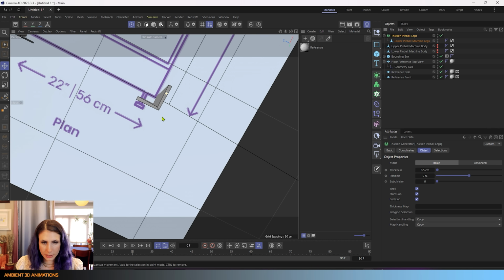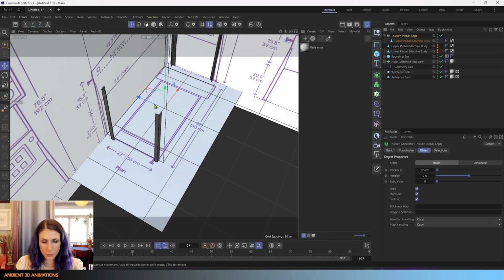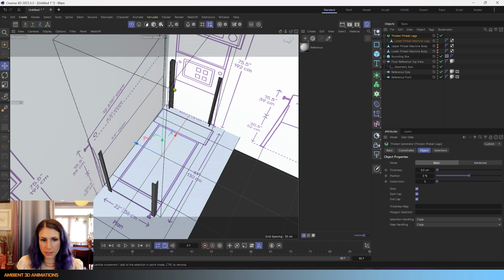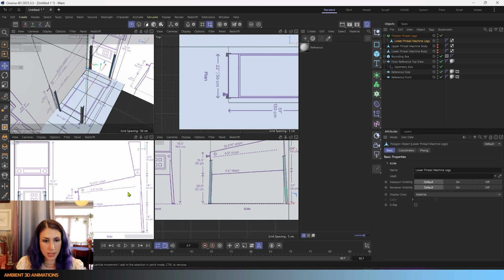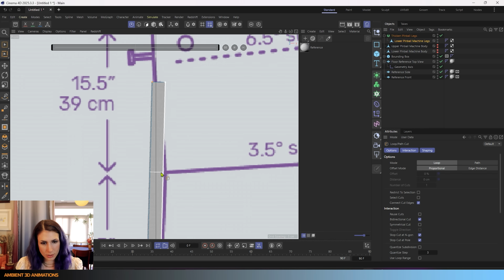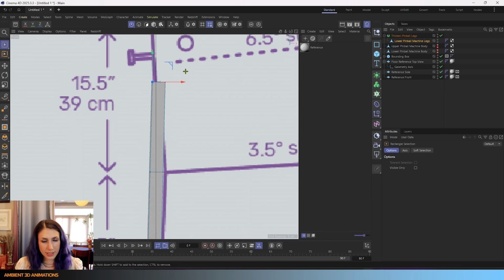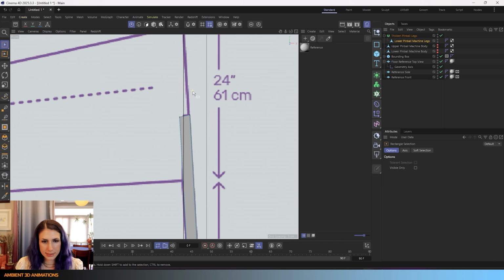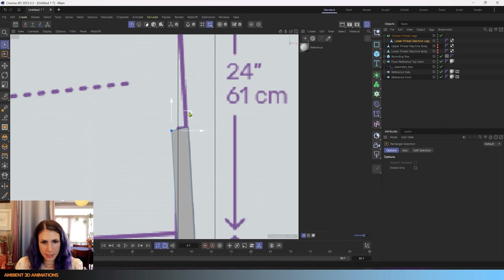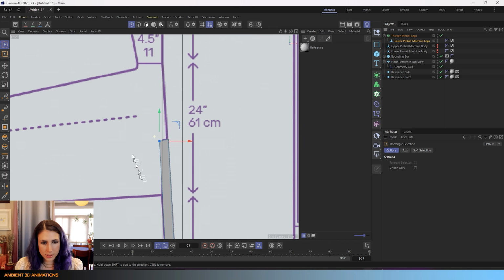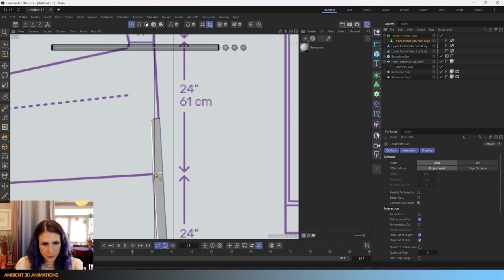So I know that's a little bit thick, but I think that when we make these voxels later, it'll be really nice. And this is something where, since it is in a generator, it'll be really easy to change in the future if we change our mind. I'm going to use ML to add in the loop cut. And I'm going to just take in these points over here, bring them on in. There we go. We're getting some nice pinball machine legs. Actually, I want to add in that loop cut here first before I do that. So I hit undo.